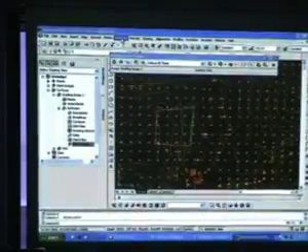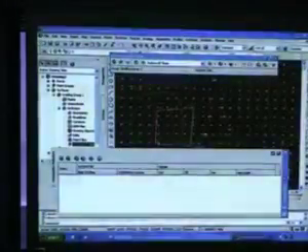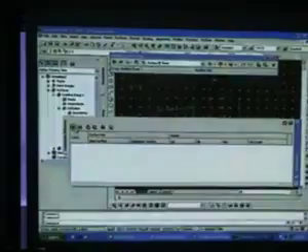Okay, I'm just going to run through the volume calculations quickly with you. Okay, so just click on volume. Then this composite volume window appears. This uses the composite volume method, which is very easy to use. Okay, we start off with the first icon. Click create new volume entry. So what you get is a line underneath here. So all you need to do is just specify what's a base surface, what's a comparison surface. Base surface means your original level.